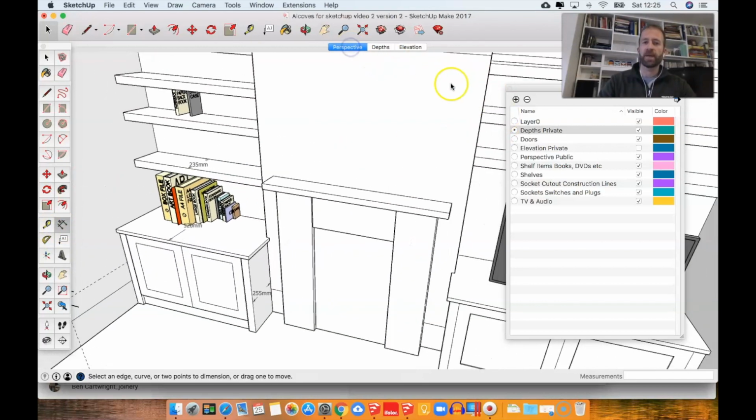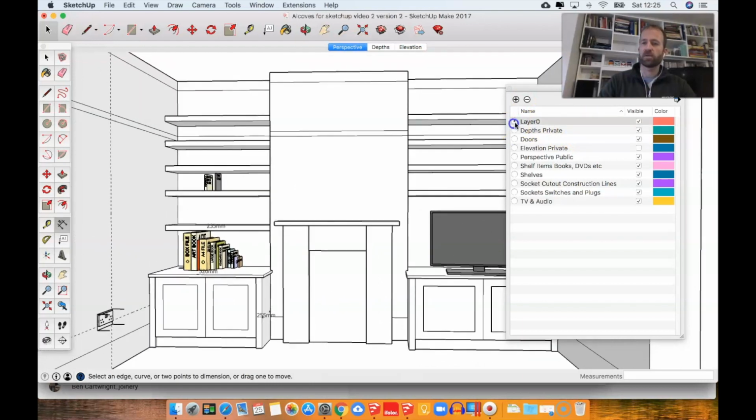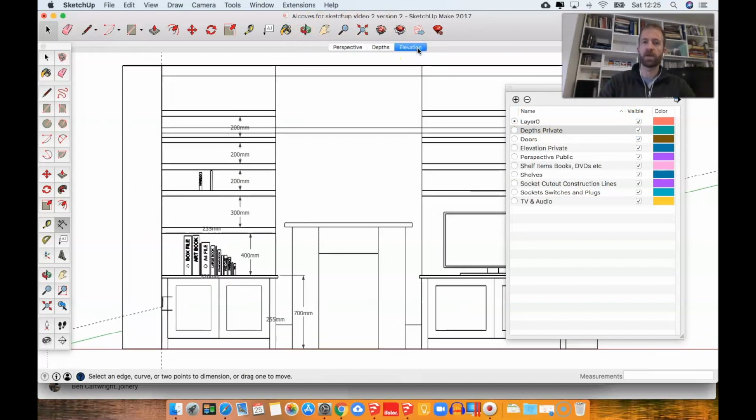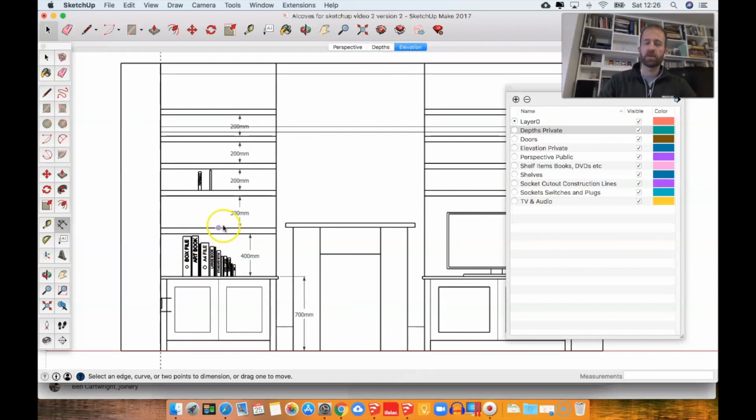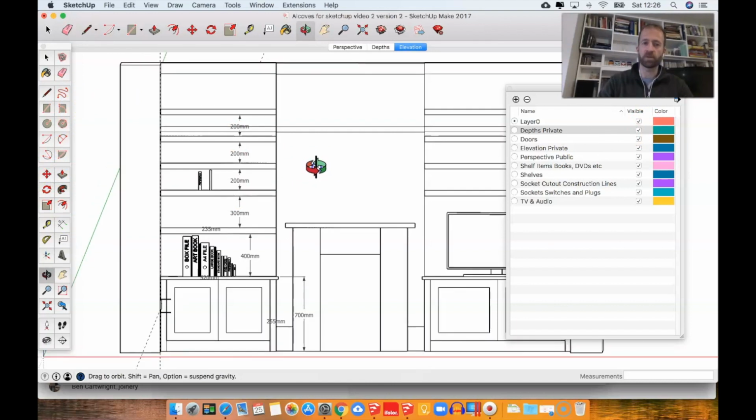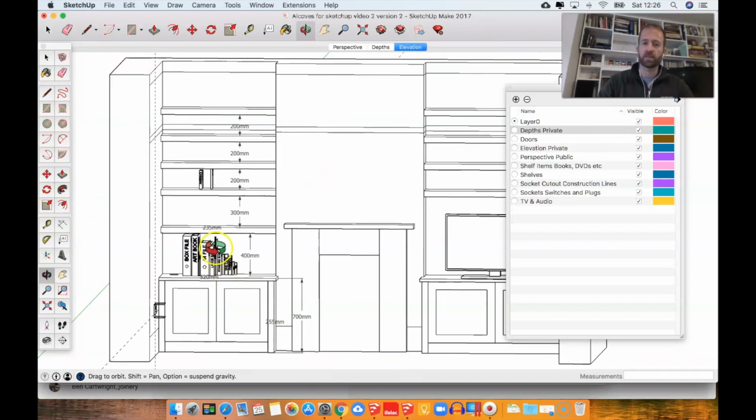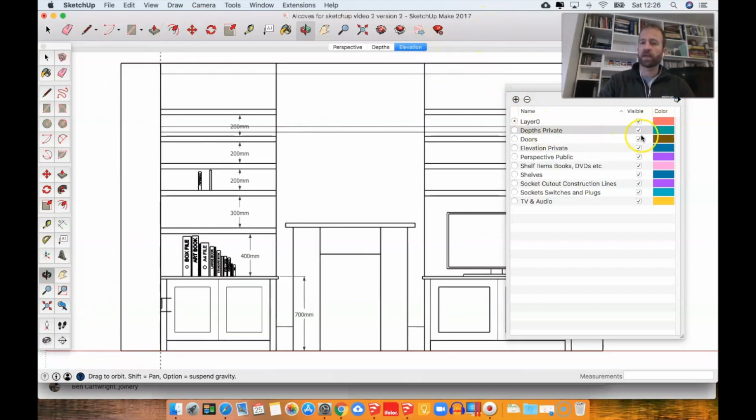and we'll go back to perspective. We'll make that invisible and update it. We'll do the same on elevation. So sometimes you actually can't see those because in elevation view it knows that they're not really relevant, but they are there and they can end up printing sometimes when you don't want them to. So if you just turn a little bit, you see they pop to visible again. So we will turn that layer off again, turn the visibility off under elevation, and update that.